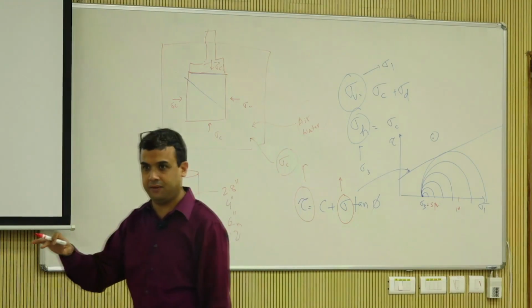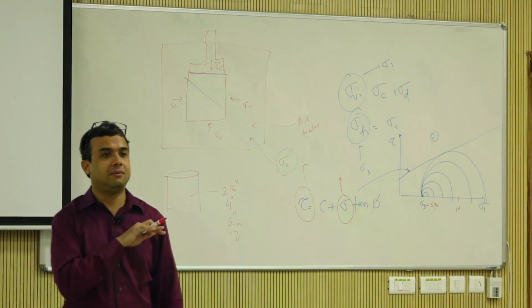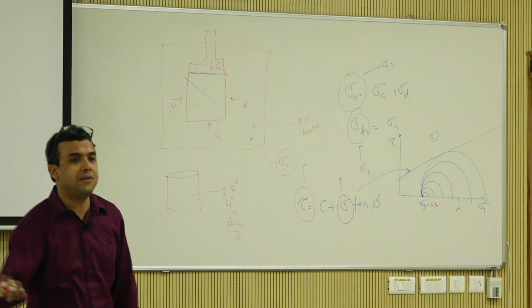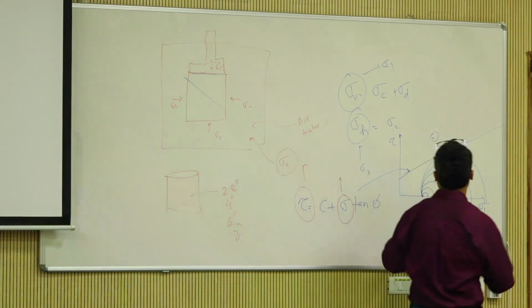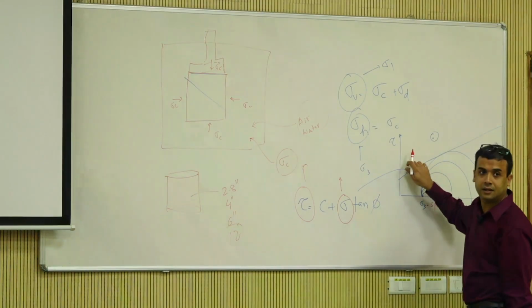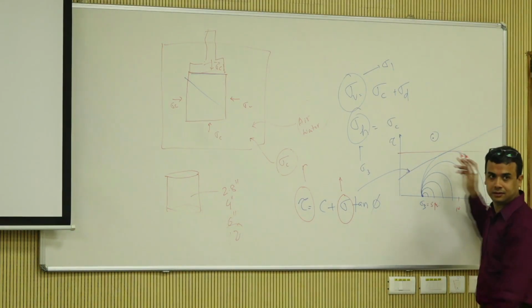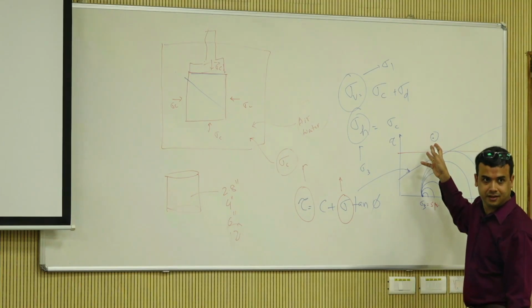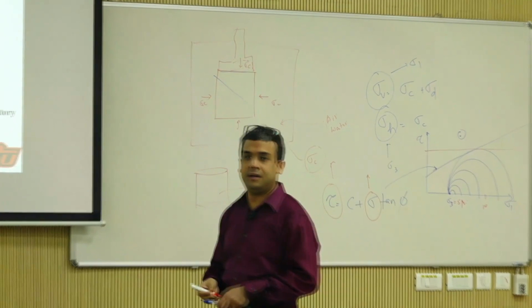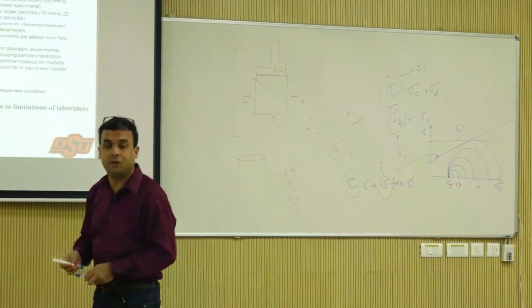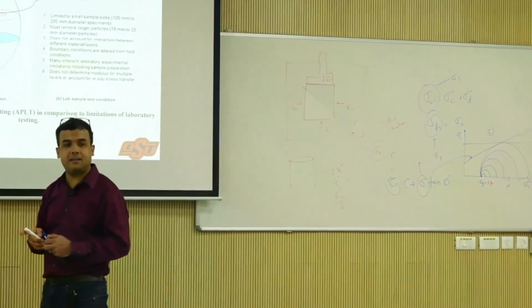That's frictional behavior, right? What if it is no friction? What if phi is equal to 0? How will the envelope look? This, right? When do you see this? Okay, clay, pure clays, yes.